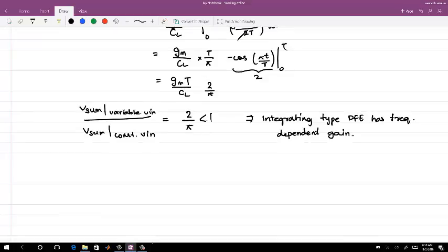Okay. Now, overall DFE which we have seen till now, there are two types. One is this resistive settling type, and the other one is the current integrating type. Let me just sum up the DFE design parameters. The first one is the input linearity, which matters in both the cases because you are cancelling the ISI with a fixed gain block.